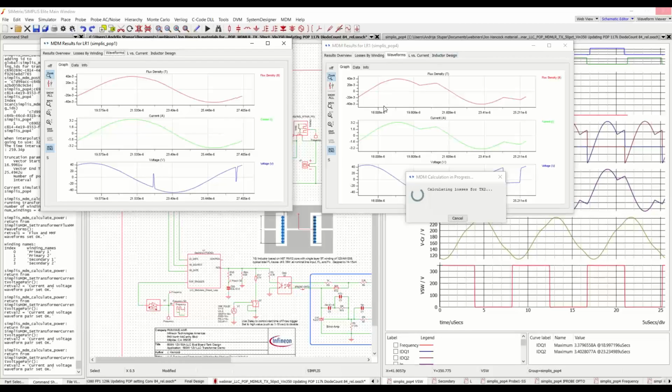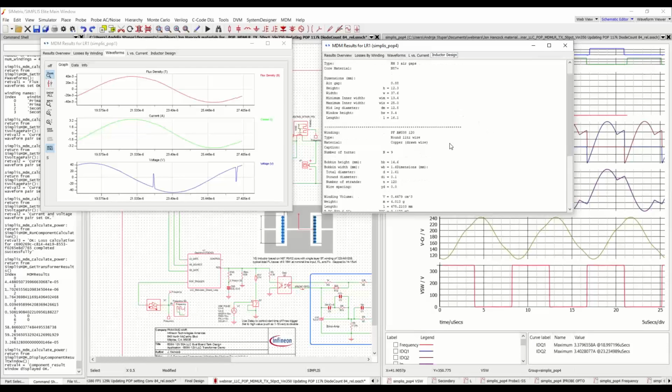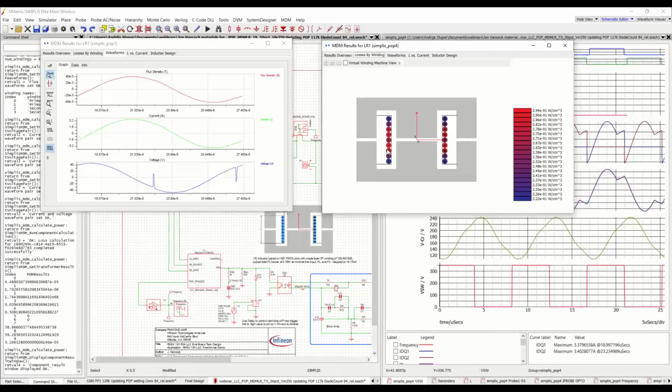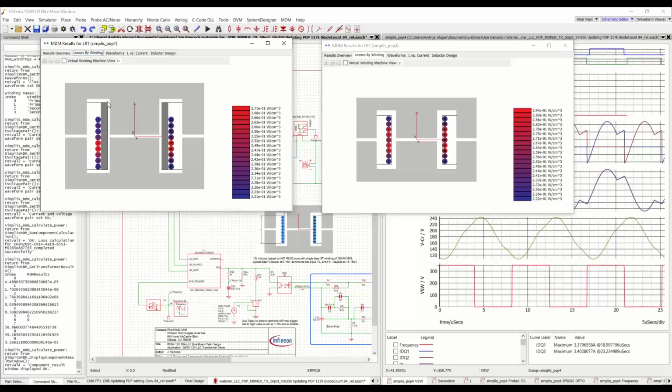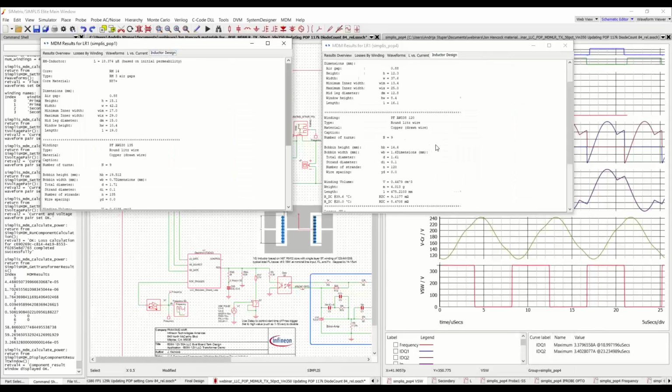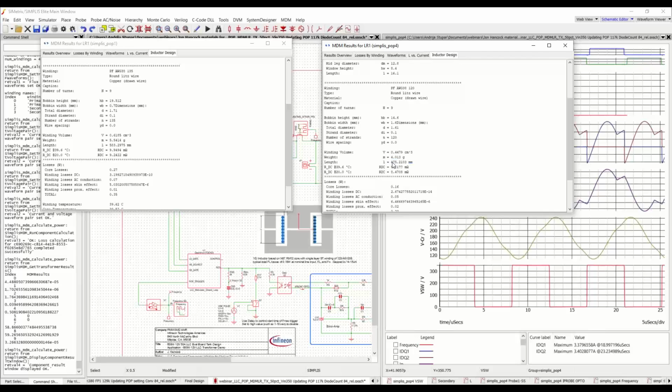This would not be the same as if we had the same flux density on a smaller core. Then our flux density would go up and then our core losses would go up, but that's not what happened here. Because of a smaller core, where we also pushed the wires all the way to the bobbin, eschewing this tape, which is reducing the proximity loss, we had a reduction in the winding length, which we can see here in this inductor design details tab. So the winding length for the revised inductor design was 475 millimeters, and for the original one, 583.